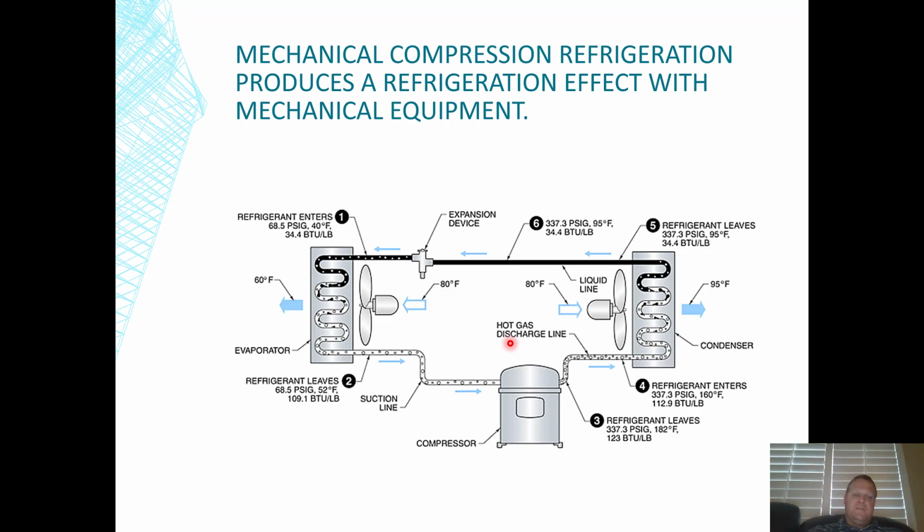All right. Now, if you think of another way to do this, what if we sent the refrigerant gas through the compressor, and it going through the condenser here, and rather than blow air across the coil, what if we took cold water and pumped cold water across the coil somehow? What if we had like a tank of water right here,